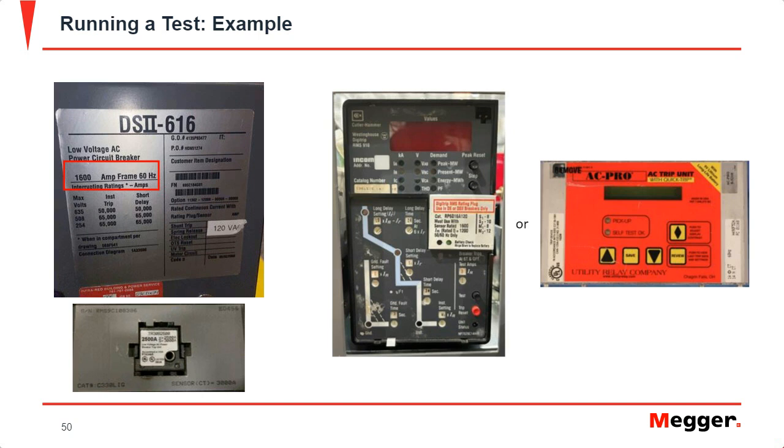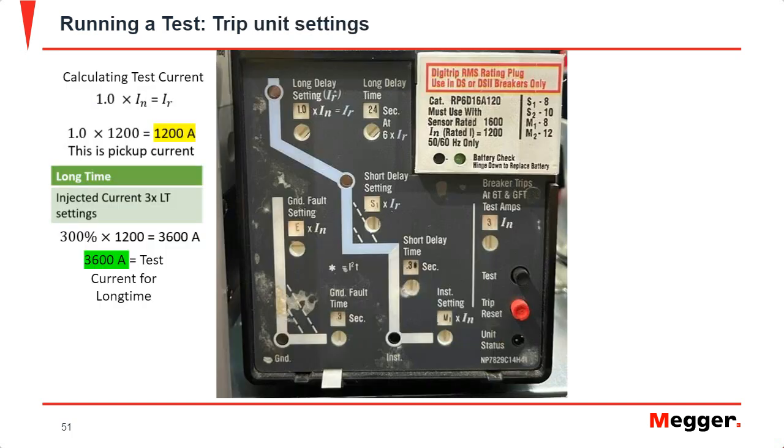We're deciding, okay, is it a Micrologic trip unit? Is it going to be an AC Pro where we actually tell it how much current will trip a long time? Do you type it in or do you actually have to set a dial? So for this breaker, we were setting a dial. And so we went through and we're like, okay, this calculation here on the left is how we found our test current. But how do I know what to look for on the trip unit to do that?